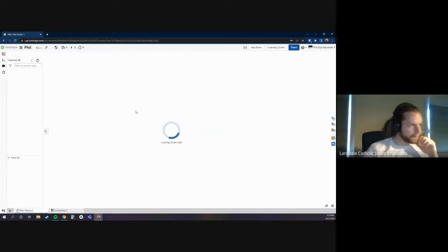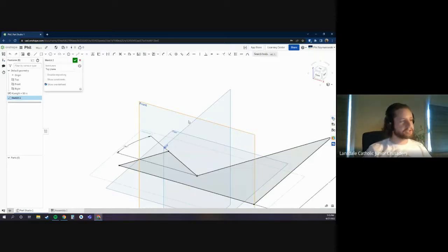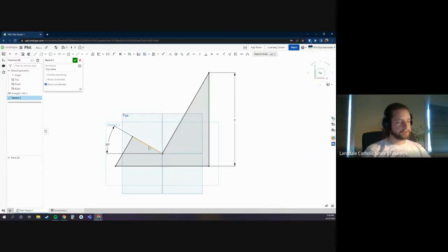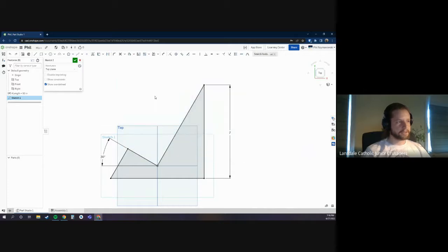And then it's also different when you're in a sketch. So when you're in a sketch, it does sketch things. So you can see I have line, rectangle, center point rectangle, circle, cut, dimension, slot. All those are things that I've added onto my little shortcut toolbar. And again, that's through the letter S. So if you're in an Onshape document anywhere and you're in this window here and you click S, you will see this pop up.